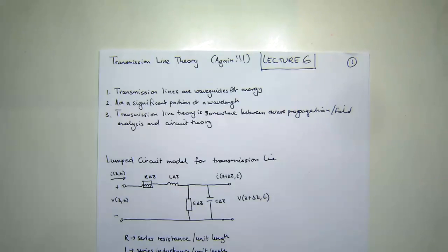Now, on a PCB board, can anyone tell me what some of the predominant transmission lines are called? The transmission lines that you usually make on a PCB board. What are they usually called? The type, sorry. What type of waveguides do we produce on PCB boards? Tracks. They're tracks, but they've got a special name, right? Who's heard of something called a strip line or a microstrip?